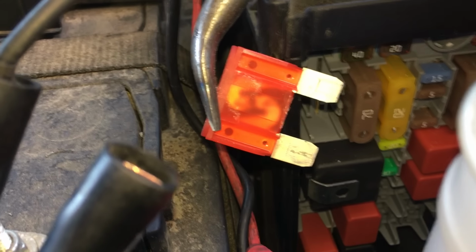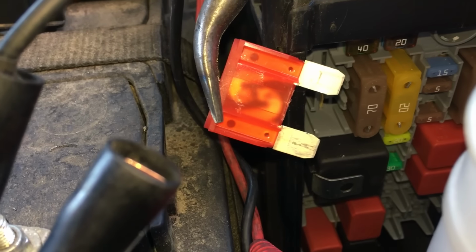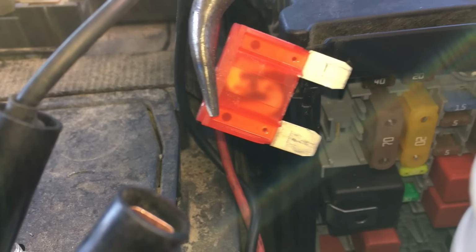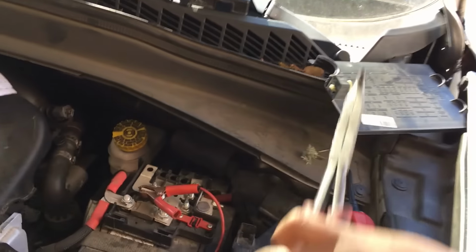And oh yeah, definitely that fuse is blown. You can see how it separates in the center. This is going to need a new 50 amp maxi fuse, so I'm going to go ahead and order that, get a new fuse put in there, and that should solve our problem with the P0481. So let's go ahead and move on to the intake air temperature sensor.